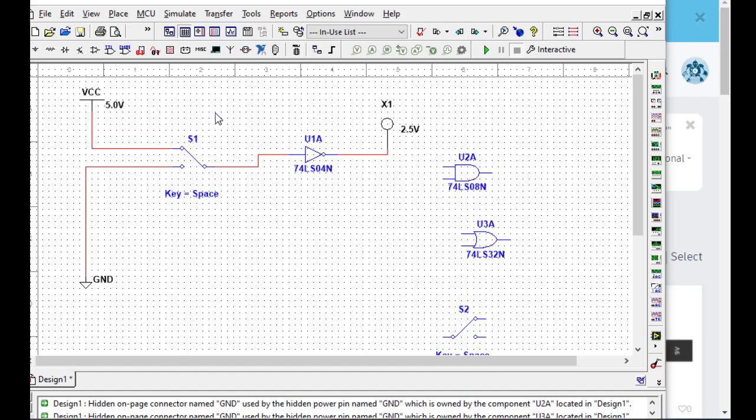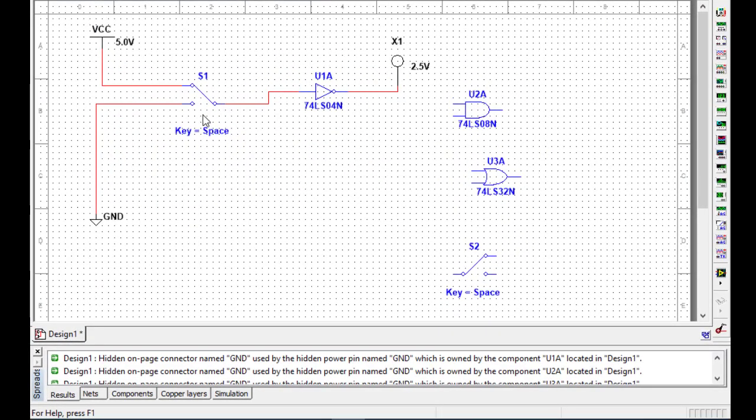So this right here is in Multisim, and this is what we're going to build first. It's just one switch, one gate, one light. And if we run a simulation, this is on right here. You can see this leads to the on, which means our light is off. If I switch this to the off, to the 0, ground is 0, so 0 inverts to 1 and my light's on. So that's how it works. It just does the opposite of whatever this is doing.